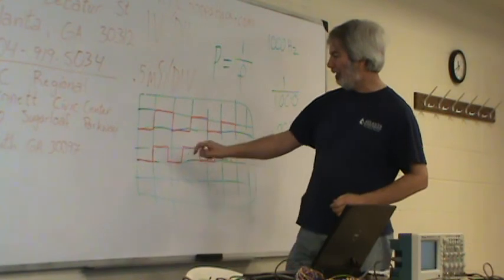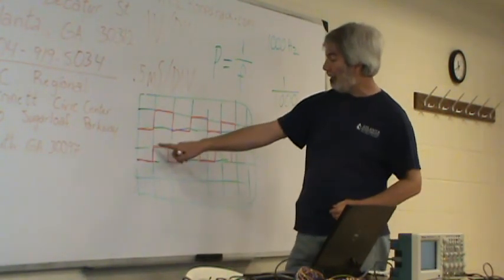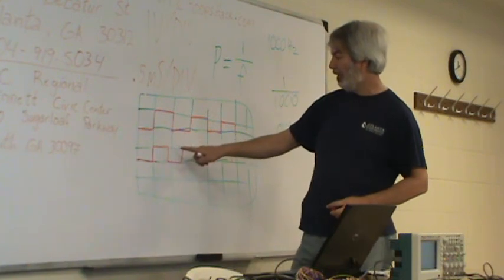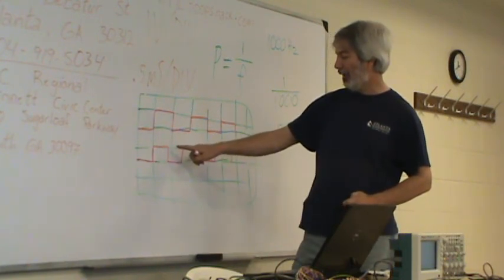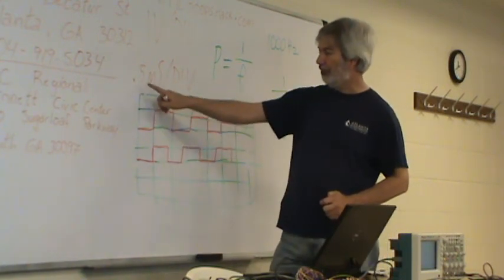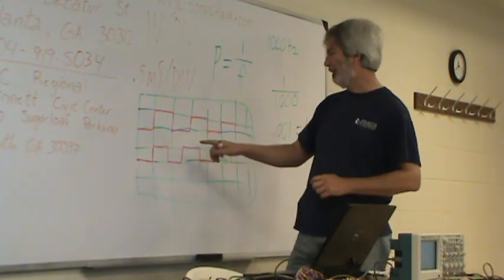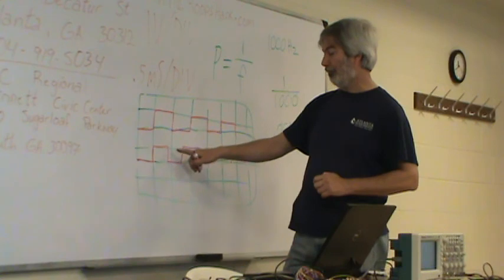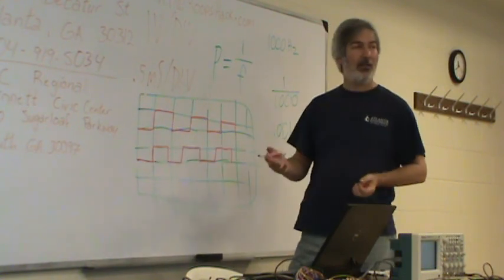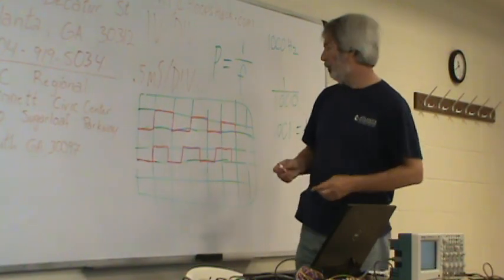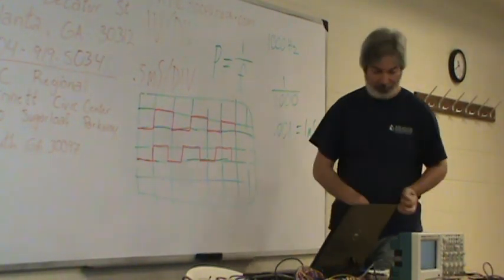But he discovers that he's not quite making it all the way over to these divisions. So this is actually taking less than a half a millisecond, or 500 microseconds, per division. So now he knows immediately, okay, it's faster than I expect. So what he'll want to do